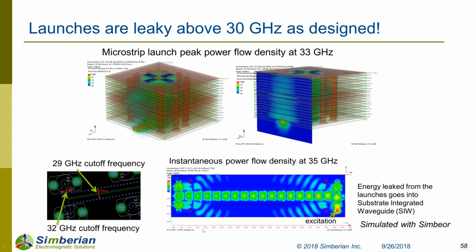So if you want to see what it takes to get your launch localized up to 60 gigahertz, there is a demo video in the demo video section where I use this launch and another one designed by Scott McMorrow for one of our validation boards with Molex, which worked up to 60 gigahertz. It was a slightly 1.8 millimeter connector from Molex.